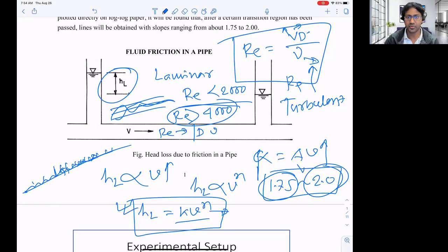So the size, distribution, and shape of the roughness matter, and we call this the roughness factor F. This factor also depends on the flow regime, whether it is turbulent or laminar. If it is laminar, we have a different formula of F that relates to the velocity and other factors.